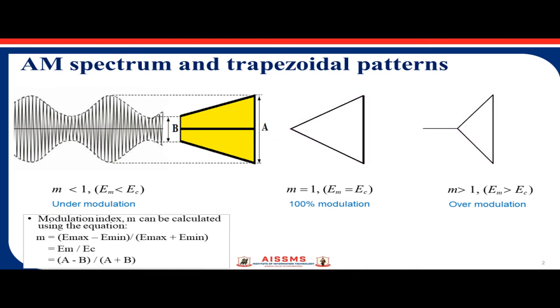For example, in musical shows, there are multiple signal sources generating at the same time. Observing amplitude modulated signals in the time domain using an oscilloscope is a difficult task because it is difficult to synchronize the time sweep. Non-periodic signals like voice signal are observed using the trapezoidal method, which is usually used to plot Lissajous curves.